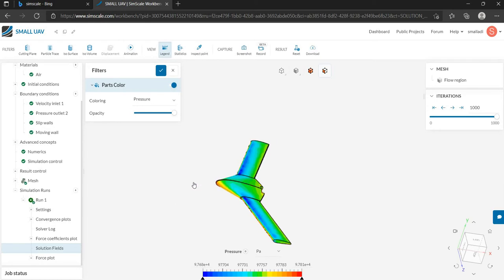The airflow over the upper surface of the UAV moves with high velocity, creating low pressure. Due to this low pressure, suction force is generated near the leading edge of the wing, which increases the airflow over the upper surface of the UAV and also increases the lift coefficient.